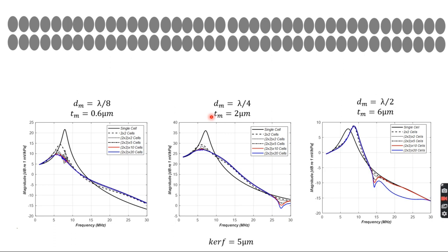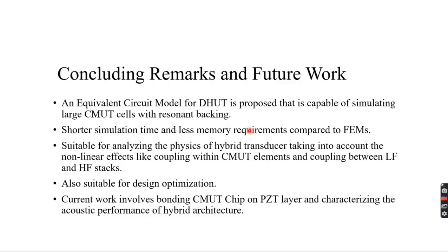So in order to use the circuit models to predict the behavior and to simulate the entire array, you can predict the response, and you can design a CMUT array for very wide band response and for the given receive sensitivity. I mean, that's how you use the circuit models. So you use the circuit models to evaluate what kind of membrane thickness and aperture sizes you will require to fabricate, to match the given bandwidth and the receive sensitivity.